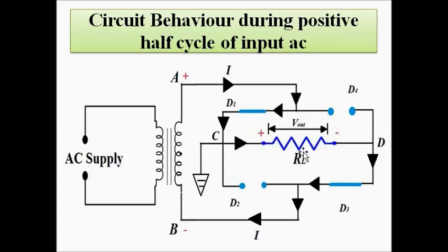During the negative half cycle also it will travel in the same direction. Only then we can call this output DC and we can get a rectified output. So always pay attention that the direction of flow of current through the load resistance in any type of rectifier should always stay the same. Only then we can call it DC. If the direction is changing, it will become AC.